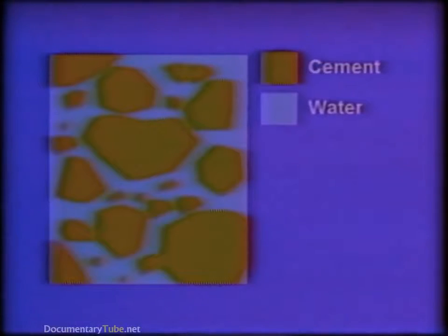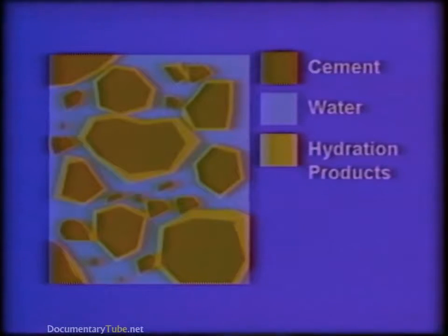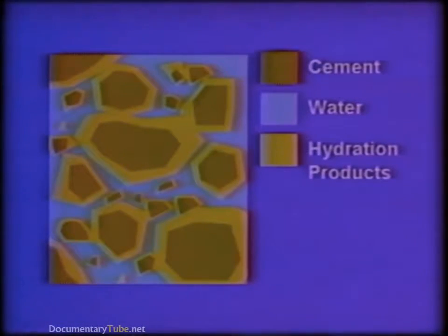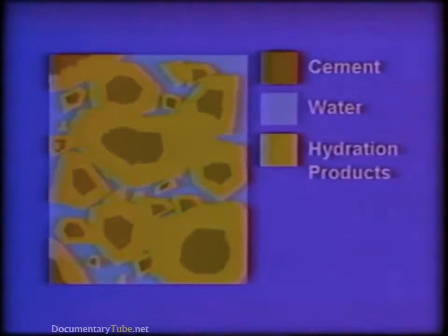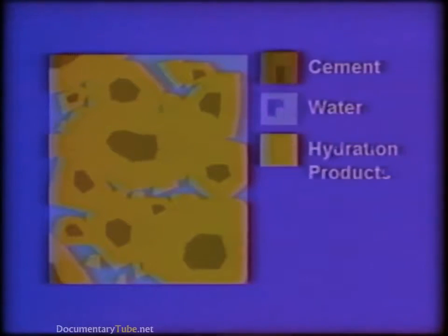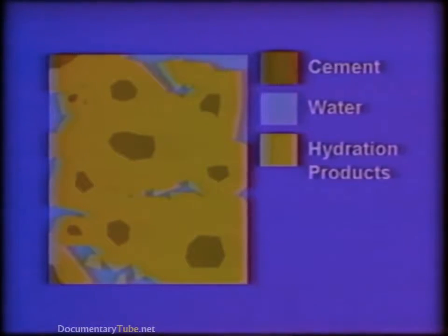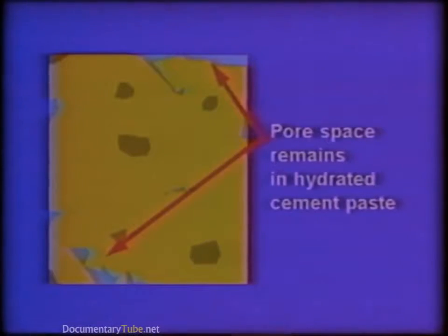This is a sketch of cement grains suspended in water. The solid hydration products form coatings around the particles of cement and gradually fill the space between. When the coatings first begin to impinge, setting occurs. There is a steady development of strength as the coatings grow together. The amount of strength attained by the mixture of cement and water depends on how effectively the space between the grains is filled up. Concrete will harden within a few hours, but hydration continues for weeks, even years after placement.